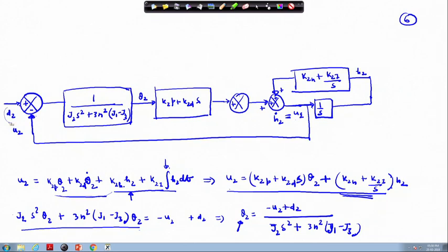If there is no disturbance, then this construction of this system is very simple. However, it requires choosing these values. Okay. So, I am showing only these constants, I have not shown their sign. So, this proper sign needs to be inserted. Okay. If there is disturbance, so those disturbances need to be rejected. So, for that a disturbance rejection filter is added here.